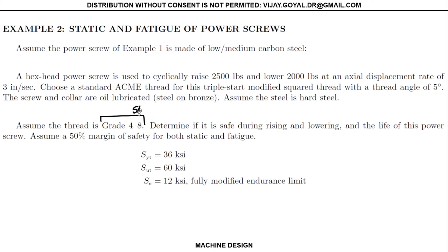We can assume that this is SAE certified, and we want to know if this is going to be safe in static and fatigue. In static, we're going to be concerned mainly with the rising, when you start rising. And in fatigue, we will worry about when it goes up and down, up and down, up and down. Okay, so let me write this down here. For static, your main focus is when you start, this is the more critical part in rise.